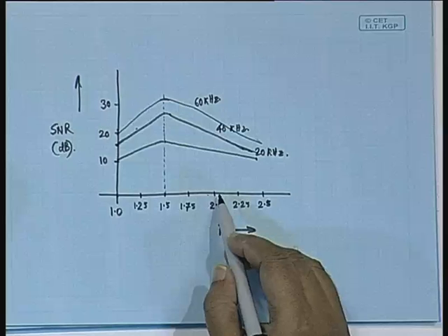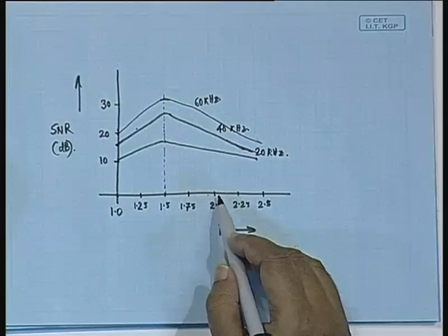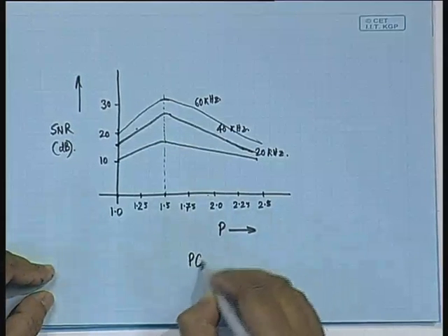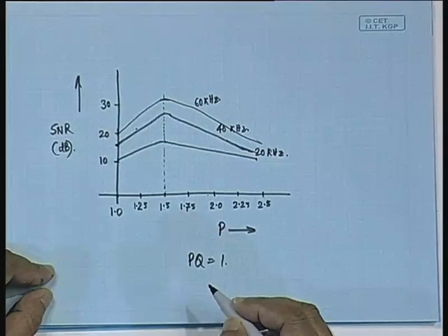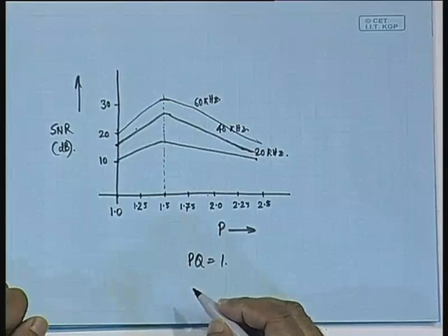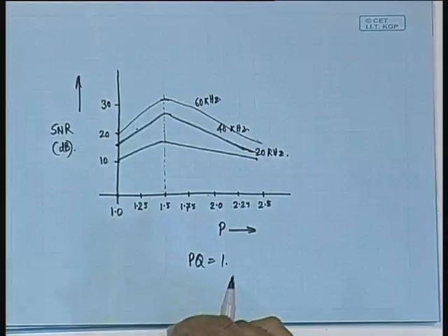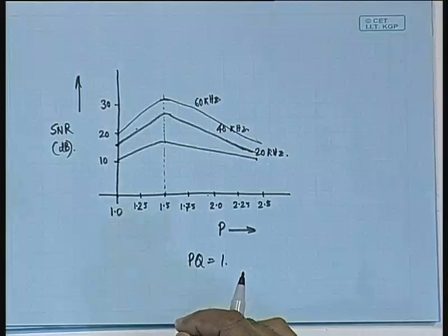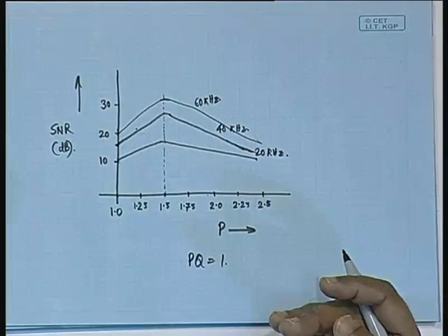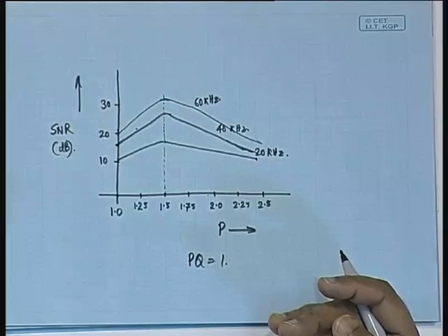Granular noise can be reduced by quickly having a very low value of Q, because if we take P equal to 2, then Q becomes 0.5, drawing this characteristic with PQ equal to 1. So next time we will reduce it, but initially we will have a higher value of P, and that would result in a large amount of prediction error. That prediction error also contributes and lowers the signal to noise ratio.